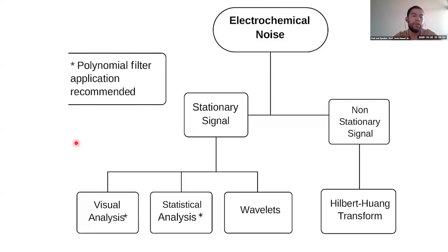When we have localized corrosion, potentiodynamic polarization or other techniques can present some limitations because they are used to determine corrosion of uniform systems. But when you have localized corrosion, electrochemical noise is the best option because it is a technique that measures localized corrosion.